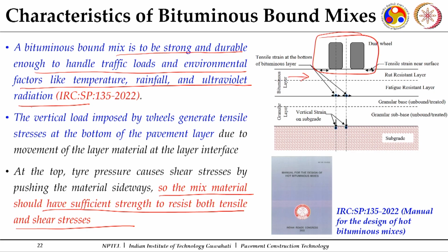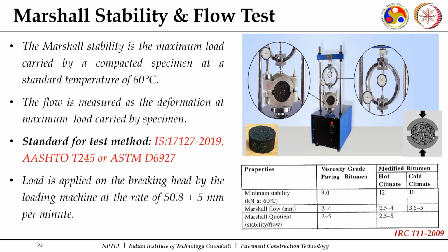This is more so in the bituminous mixes. Three parameters are mainly evaluated for the bituminous mixes. There are many more parameters, but the three basic parameters ensured during the design of these bituminous mixes, one is the Marshall stability. A cylindrical specimen is prepared in the laboratory with a particular combination of aggregates and binder and is subjected to loading.